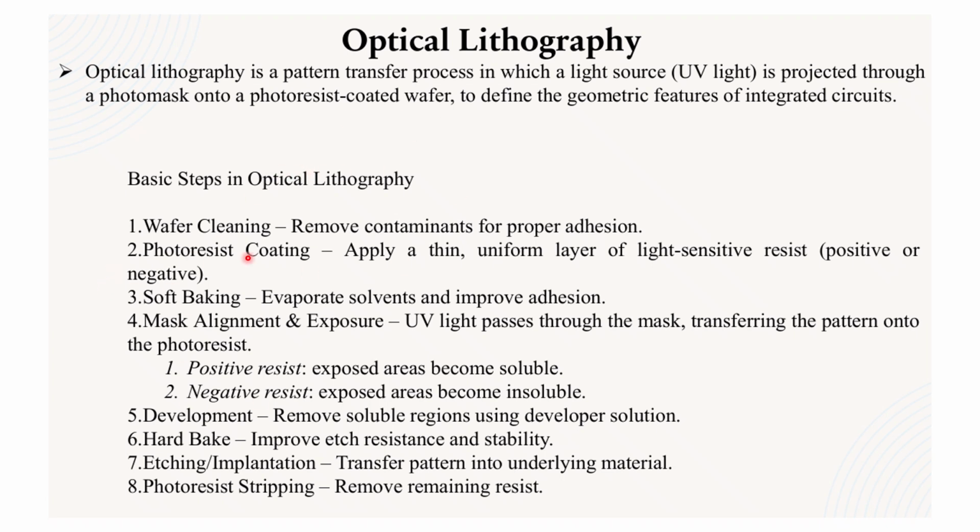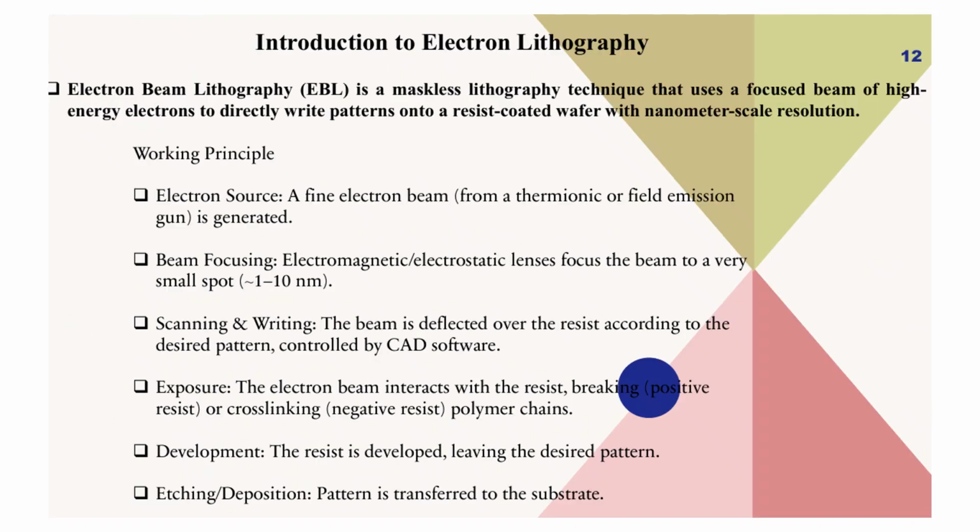So these are the steps: you should prepare the wafer with photoresist. Because of the photoresist, you will do soft baking to make it hard, that is just applying temperature so that the solvent evaporates, nothing else. Then mask alignment, which is also important for the photoresist, and development, hard bake, etching and implant. Etching is just the removal of unwanted layer.